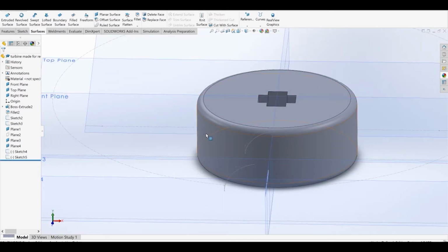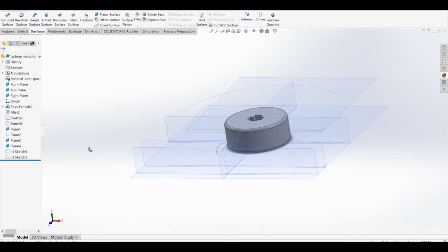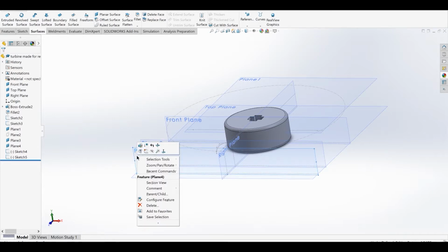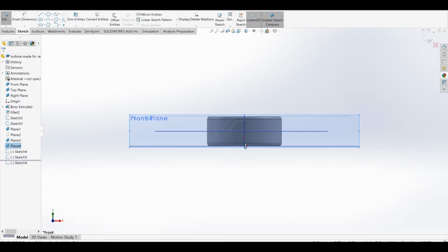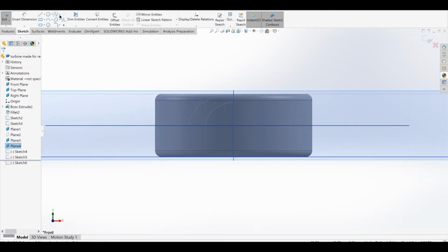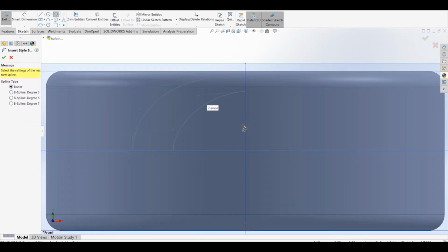Now obviously at the end of the blade there's nothing, but we shouldn't use a point to create our last profile, because that can create problems down the line when we're trying to make a surface. So what we can do is extend our blade out near to the tip but not at the tip. So we'll sketch on plane 4, look at it head on, and insert one more curve that's just significantly smaller than these two, but not too small so as to cause us problems when we're creating the geometry we want.